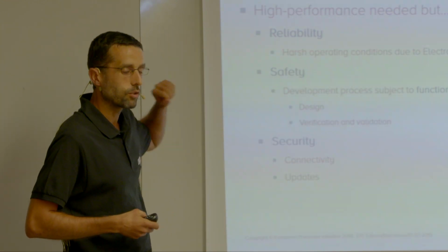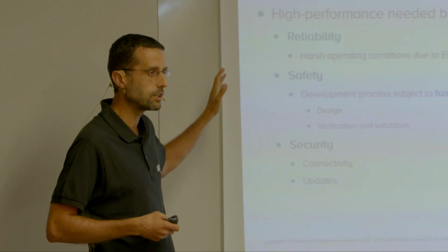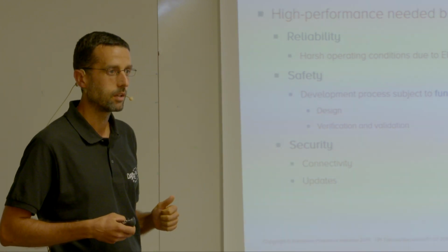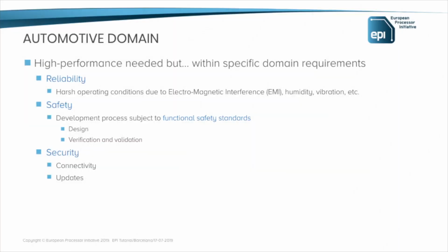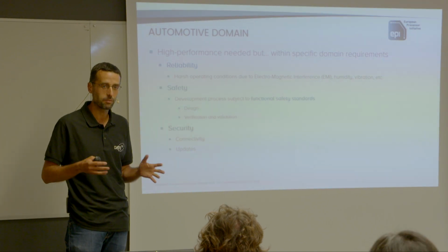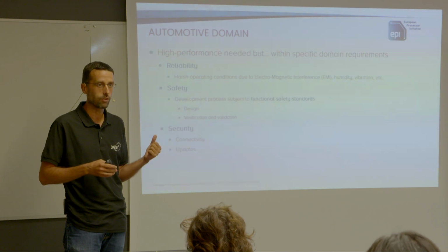So, in the particular case of the automotive domain, we have a number of requirements that are common to other domains, but specifically relevant for automotive. One of them is reliability. You can imagine that your computer may be sitting next to an engine, perhaps operating at 60 or 70 degrees. Very likely you won't have a fan, simply because these mechanical components will tend to fail, especially in such a dirty and noisy environment with so many vibrations. So it's a very tough environment where components suffer a lot.